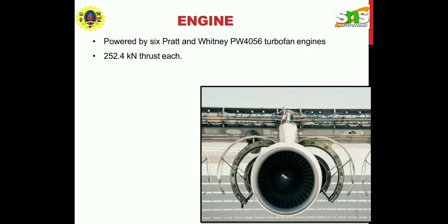Reaction turbo machines operate by reacting the flow of fluid through aerofoil shaped rotor and stator blades. The velocity of the fluid through the set of blades increases slightly as it passes from rotor to stator, and vice versa. Newton's third law describes the transfer of energy for reaction turbines. A pressure casing is needed to contain the working fluid. For compressible working fluid, multiple turbine stages are usually used to harness the expanding gas efficiently.